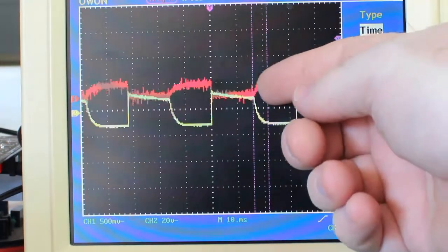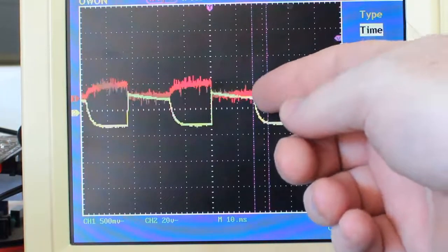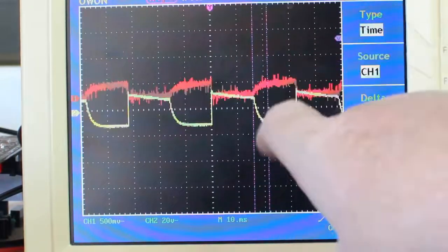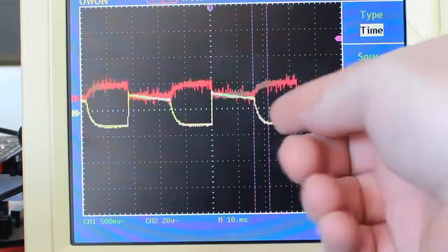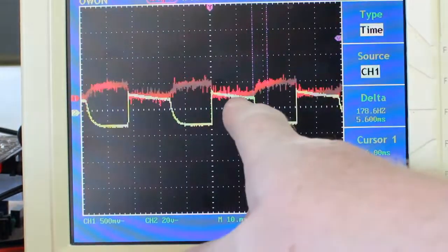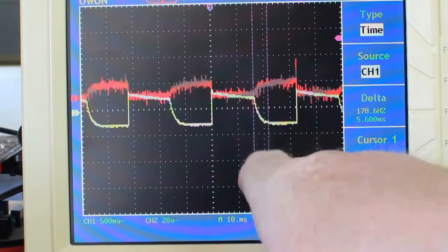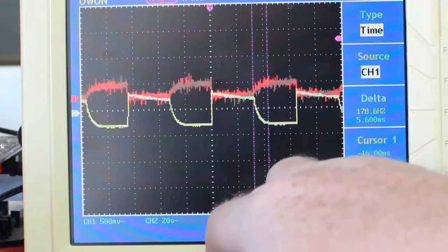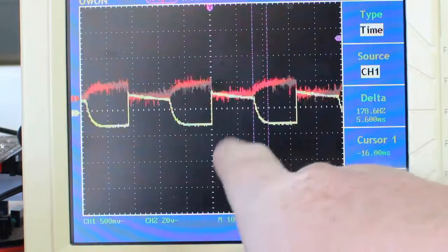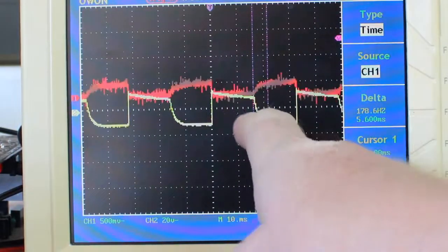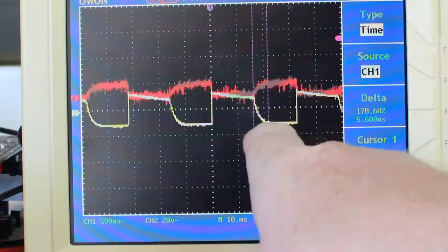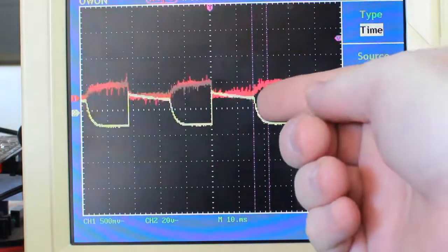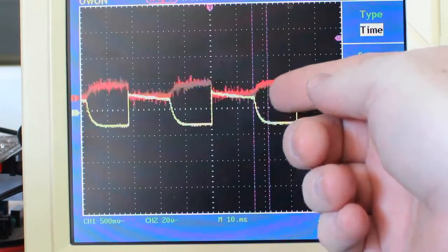It's the time rate of change of the magnetic field of the current, which is the curve in here, that generates a voltage. The faster that happens, the more voltage in a shorter time will be generated. And "generated" should always be put in quotes, because it's never really generated at all. It's already in the material. But anyway, you can see that there is a changing voltage, and the changing voltage aligns almost perfectly with the changing current on the red one.